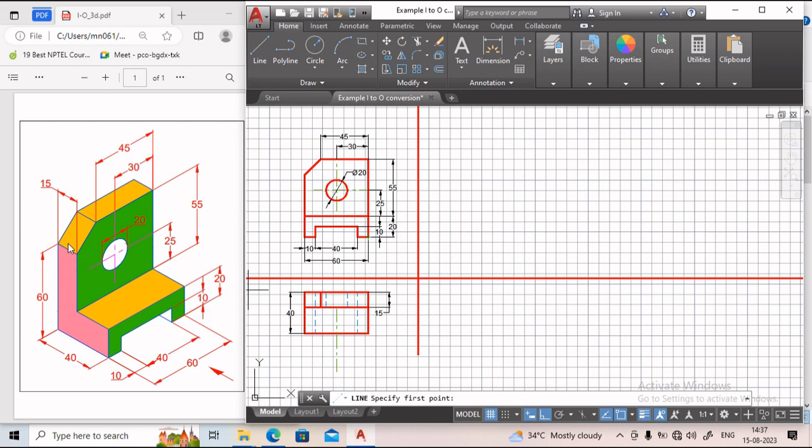Okay. Now in the side view, say if you want to start the drawing with this point, then basically this point in the front view and this point in the top view are this point. So we can project this point first onto the vertical reference line. Then we have to draw the 45-degree line. To draw the 45-degree line, we will press tab, and after pressing tab, you will be able to place the angle. Now the angle is given as 0 degree.